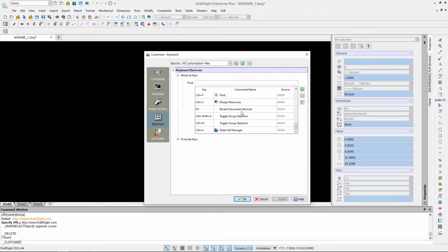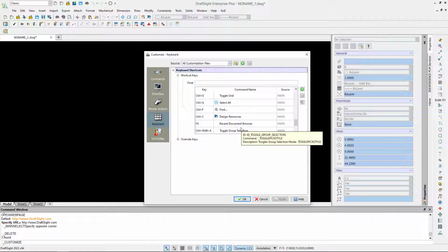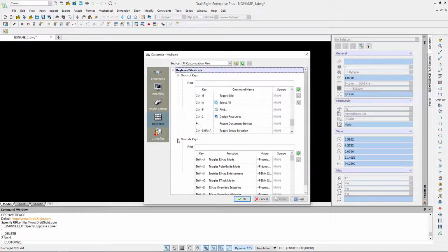And where it gets really interesting is down here there's our shortcut keys, our F or function keys. You can actually assign the function keys a different thing. So like F5 for me in a browser is refresh. Now, DraftSight has a command where you can kind of redraw the screen. So one of the things I like to do is I'll go in and hit this plus sign, hit the F5, and assign that to the redraw or refresh command inside of DraftSight. And then the override keys are just looking at it and saying, well, Shift A versus Control A, that type of thing.